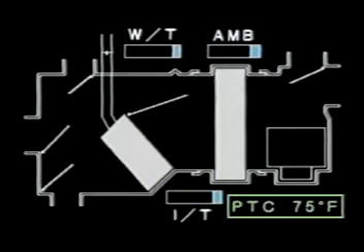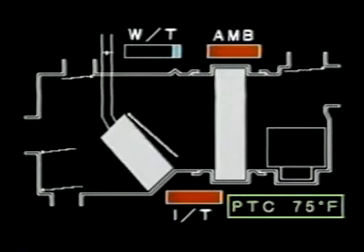Next, let's look at the differences in operation between the setting at 75 degrees Fahrenheit and 65 degrees Fahrenheit in the summer. Let's press the auto switch and set the temperature at 75 degrees Fahrenheit. Immediately at this condition, the automatic air conditioner reacts to cool the vehicle because the in-vehicle and ambient temperatures are high, and there is a large difference from the set temperature.